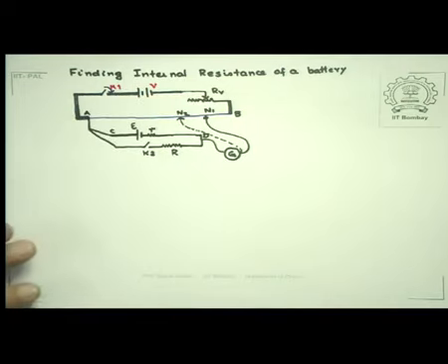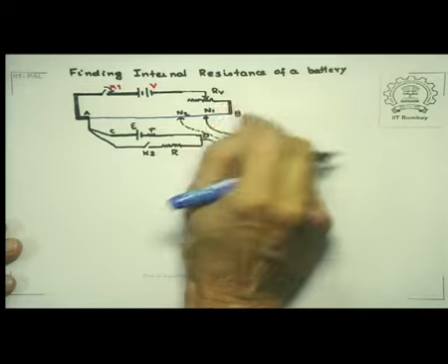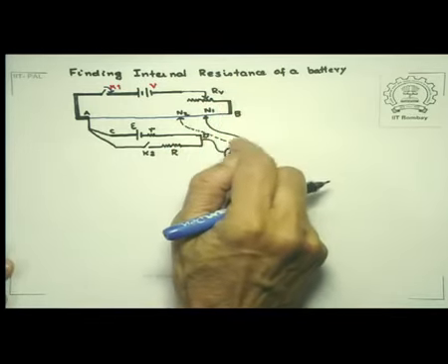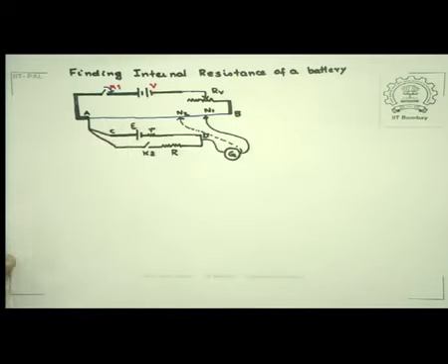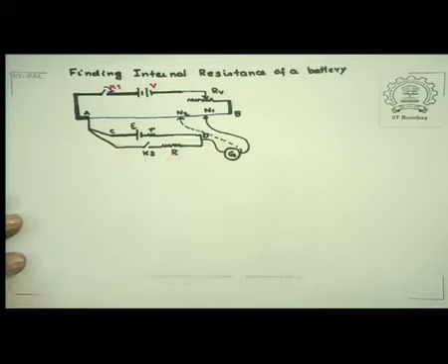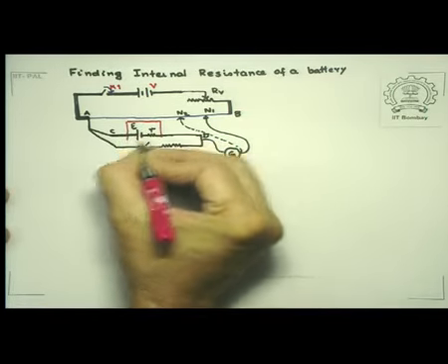remain closed. There is a variable resistance RV as before, which is adjusted so that the galvanometer reading comes between the section A and B. Now there is a modification in this part of the circuit. This is the EMF whose internal resistance we are interested in determining.